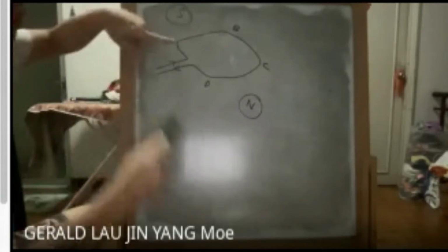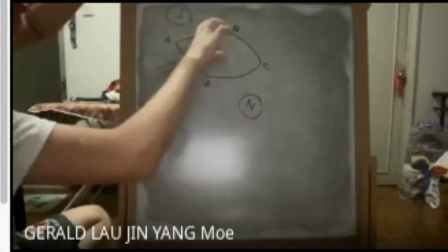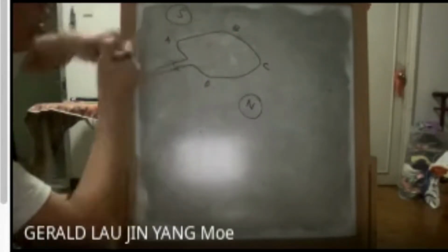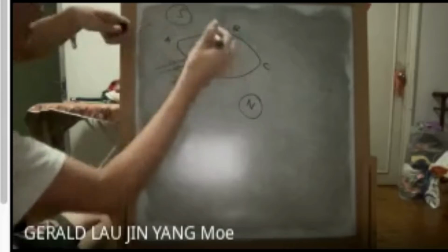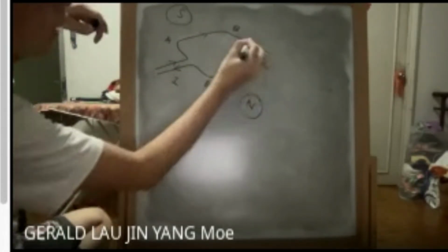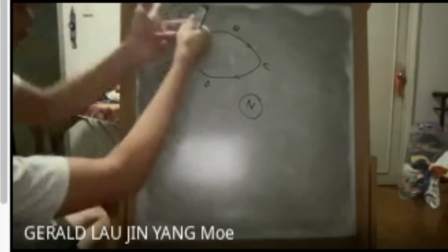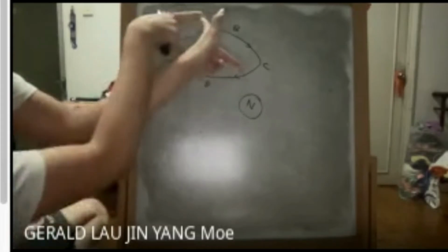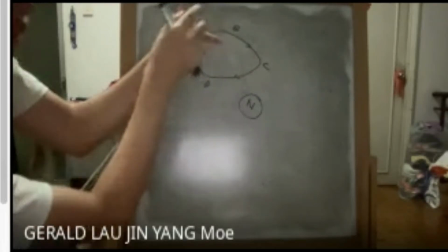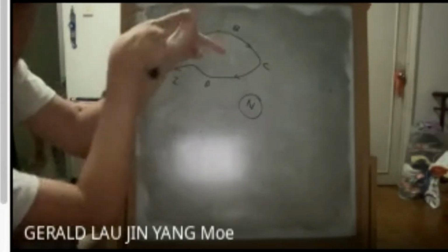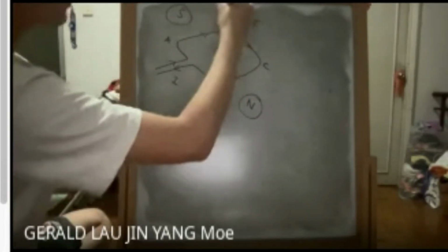You want to determine which direction this will spin. So you need to find where the force is. You have your current, you have your magnetic field, so you have to determine the force. Now we look at this part first, for AB. For AB, how is the current? Fleming's left-hand rule, current moving like this. Magnetic field moving over here from the right to the left. Current is heading towards here. So with Fleming's left-hand rule, your thumb, the force, will be pushing upwards. That's why the force for this side is going upwards.